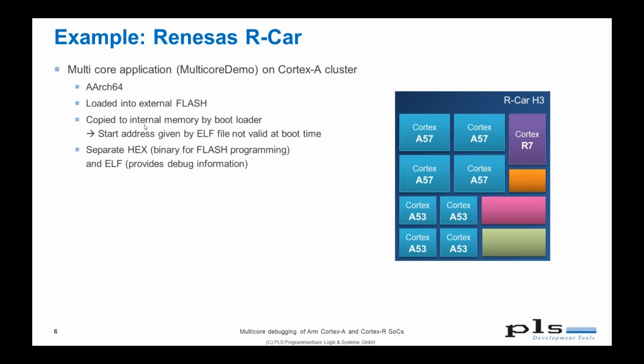And that results in the need that this application has to be copied from the external flash to the internal memory of the device by a bootloader that we have to provide. So this means that the start address of the Multicore Demo application, which is given in its ELF file, is not valid at the boot time. And it's the first thing that you need to know when you set up a debug session.